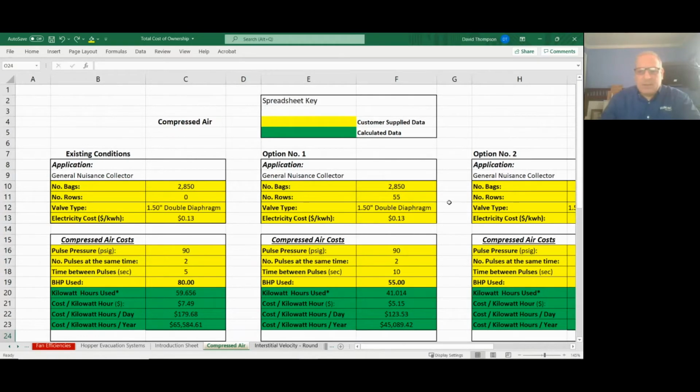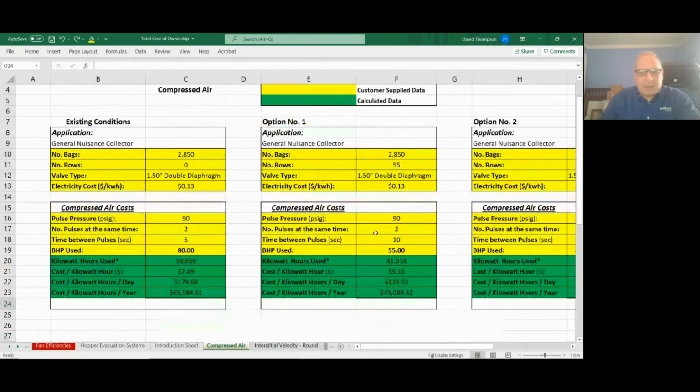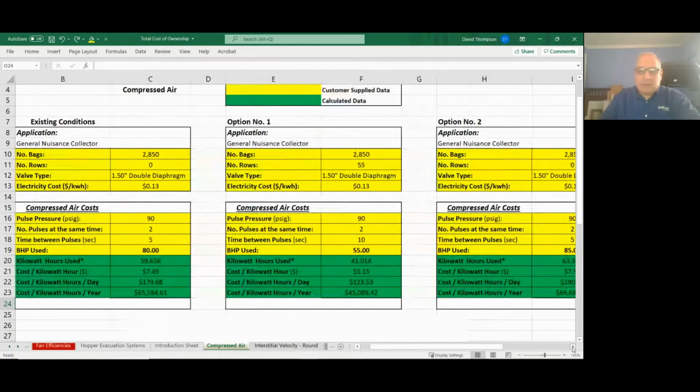So when you look at these different scenarios, we talk about using all the same type of cleaning system for all of them. But when you change the time between cleaning cycles, you pulse less. Therefore, you consume less air and less energy. In the low drag bags, which tend to get to their differential pressure and flatten out, you'll find that they're the least expensive to pulse. They may cost $15 more per bag, $20 more per bag, but in the end, when you're pulsing much less and less frequently and using less energy to do it, you are creating a good situation.